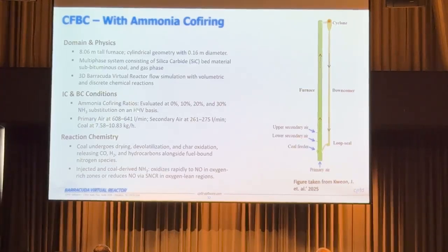And then, if you look at actually the chemistry in the paper, all these steps that I showed previously, whether that is the pyrolysis, the devolatilization step that happens, the char oxidations, the gas reactions, the reactions on the NOx formation, all of them are very similar in this paper. Now, the kinetics itself are different. They are obtained from their own sources, but all those steps are quite similar.